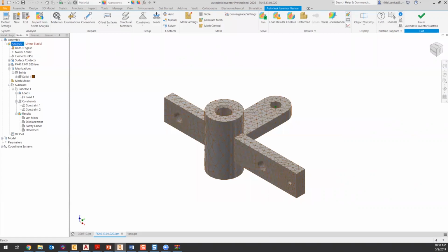It'll be one PKG file per assembly, yes, but that one PKG file can contain as many things as you want. So if you had 4 or 5 different analyses here, different types of analyses, say a linear static, normal modes, a non-linear, etc., you can still create PKG files and associate them with the CAD model.